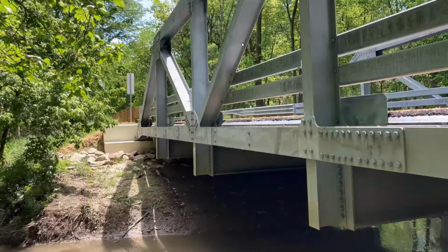And in this oblique view, you can get a very good view of that twin steel plate monochord that has the integrated gusset plates shaped within the plate that creates the bottom chord. This bridge has a fairly low crossing, so you can see that was a consideration why the truss bridge replaced another truss bridge.